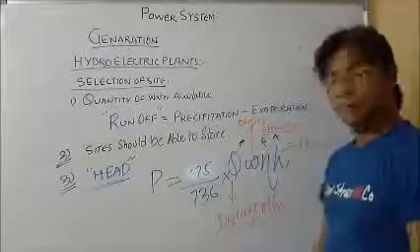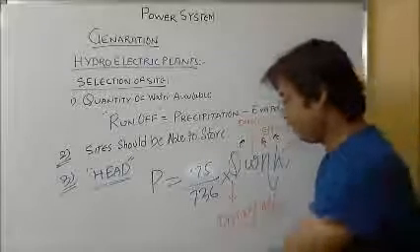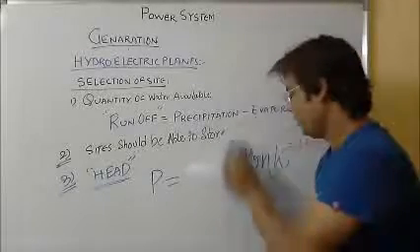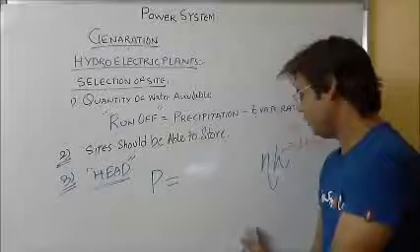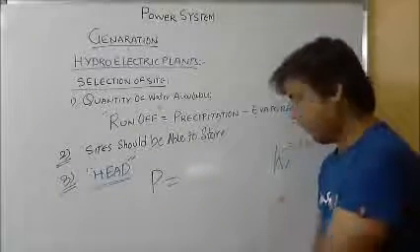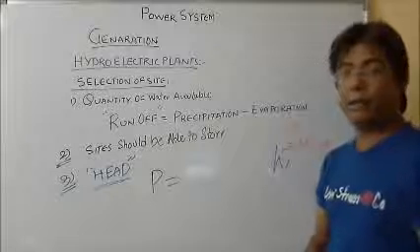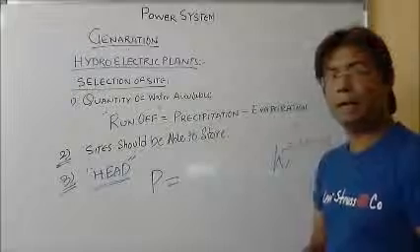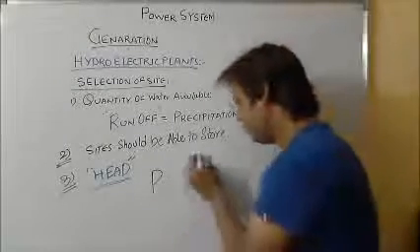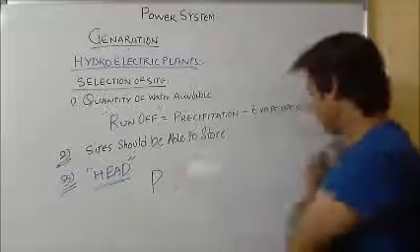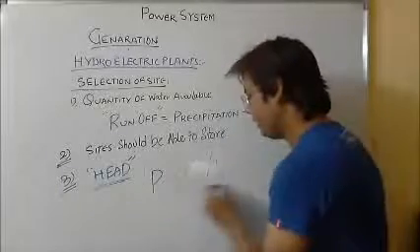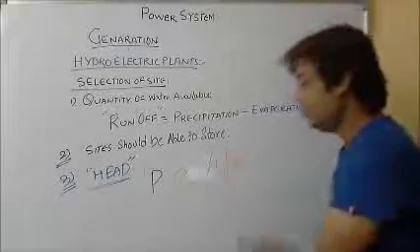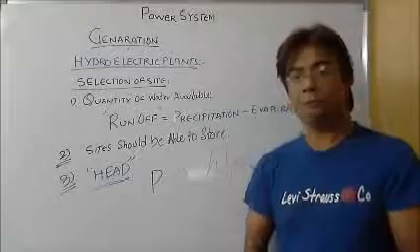So from this formula we can say that the density is almost a constant, Q is also almost a constant, and for a plant, efficiency is also a constant, or even if it is not, there is not much difference between hydroelectric plant efficiencies. So we can directly say that your power is directly proportional to your head. This is a very important relationship: generated power is directly proportional to head. Please remember this for objective type questions.